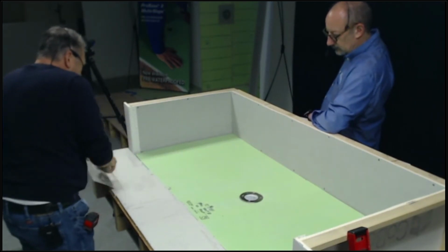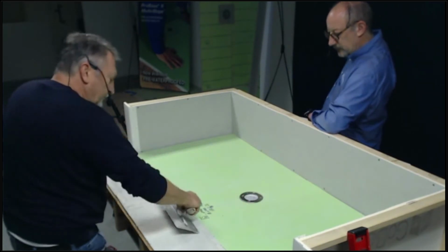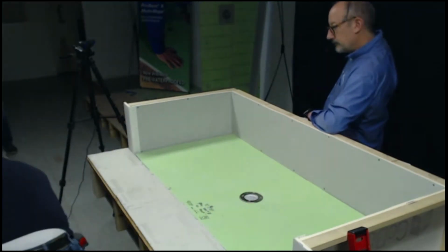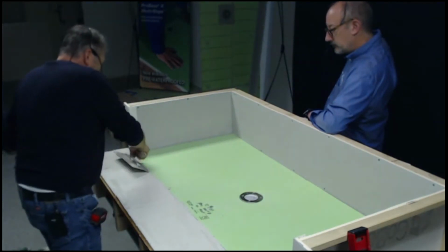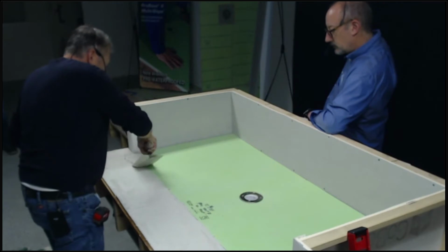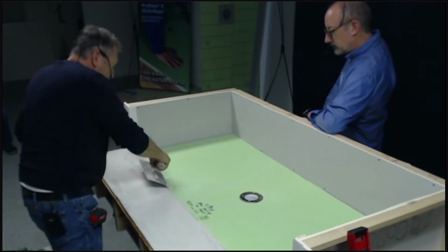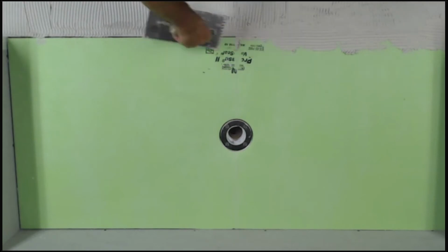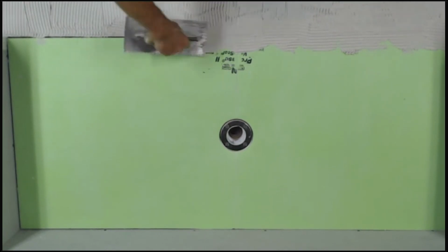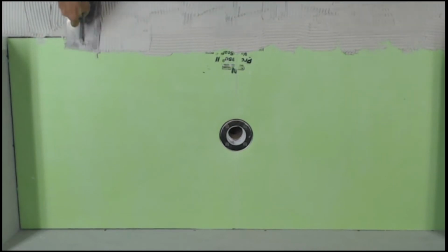Now, the membrane, I'm going to use Valu-Seal membrane in my dry space, but I also want to transition that out to my base. So I'll go ahead and put a couple inches out into there. I always do think that in a lot of these jobs, by the time you go a little bit out of the shower, you might as well do the whole bathroom area. Exactly. In this case, it also would offer crack isolation.